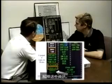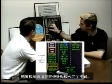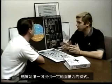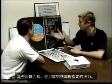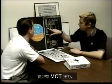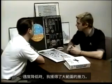Speed Mach. Explain those FMAs to me. Speed Mach is completely different from these other engage modes. Speed is the only mode where you have a range of thrust available. In all these other cases where it says thrust MCT, or thrust climb, or thrust idle, or even thrust lever, you are only getting the thrust that's named there. I have MCT thrust only. Down in speed, I get a wide range of thrust.